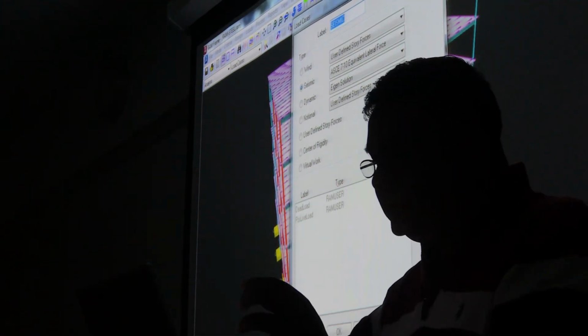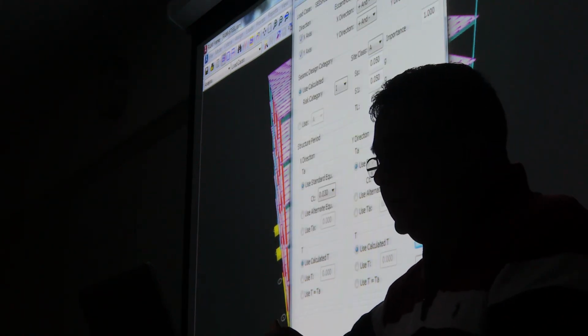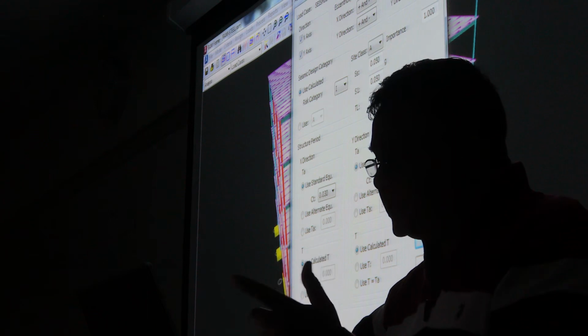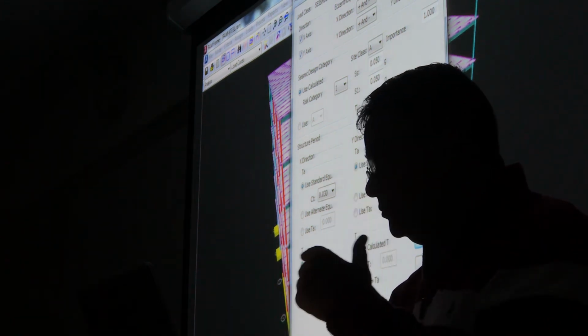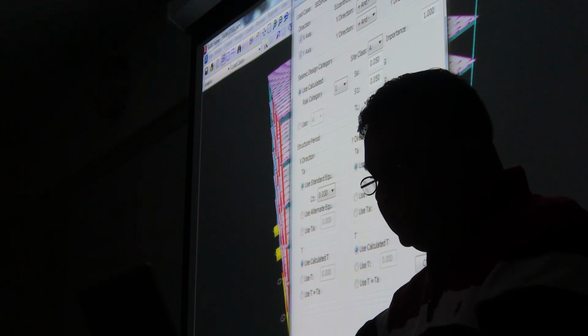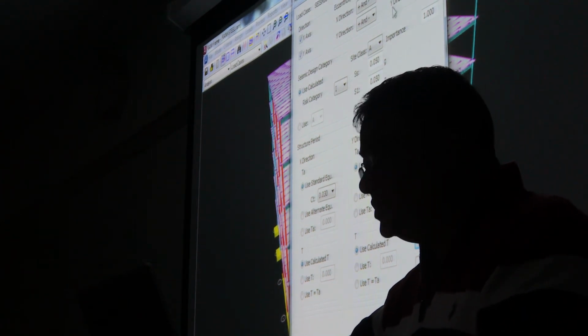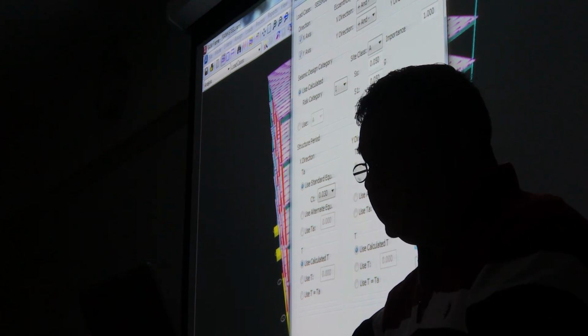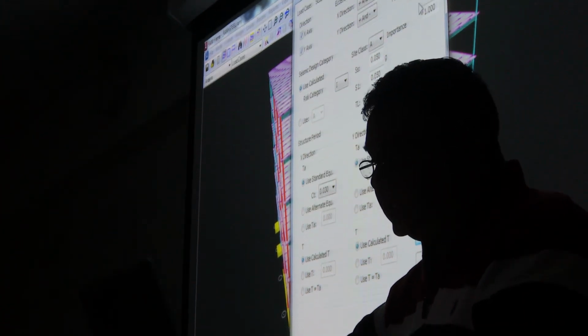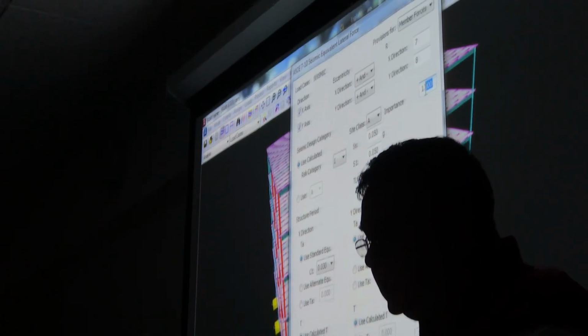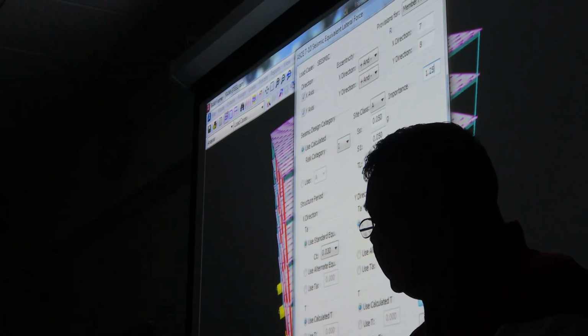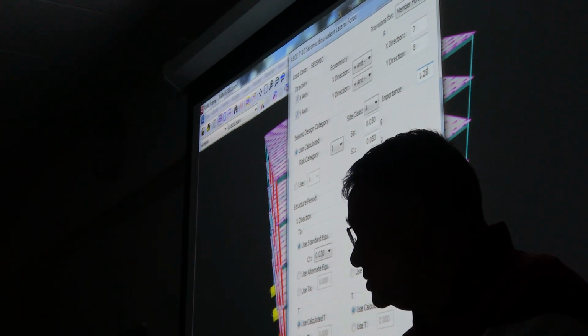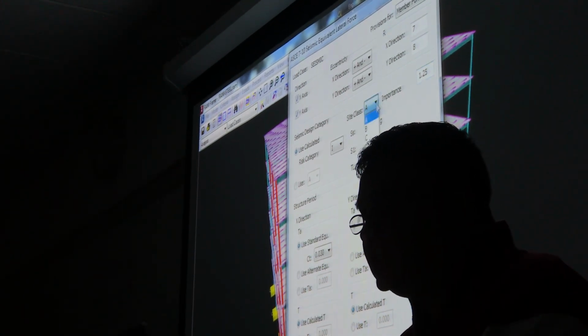So I'm going to change a bunch of numbers. In the X direction we have brace frames, eccentric brace frames. That's actually 7. Sorry, special concentric brace frames is 7. In the Y direction it's special moment frames. That's 8. These are called response modification factor, R factor. You will learn it in your senior design. Importance factor for this building, office buildings are usually 1.25, that means it's multiplied by 25% more. Soil site class D, if you do not have that.